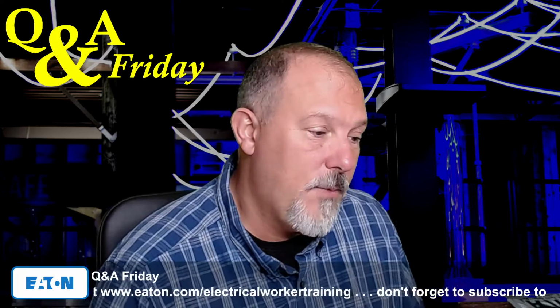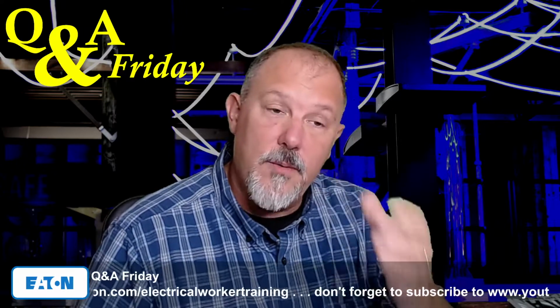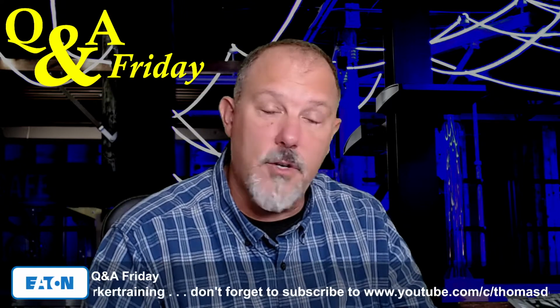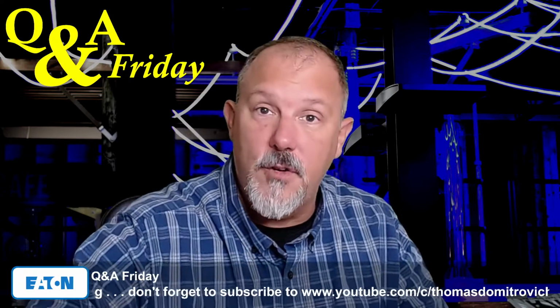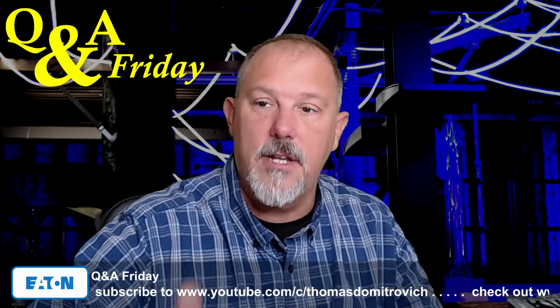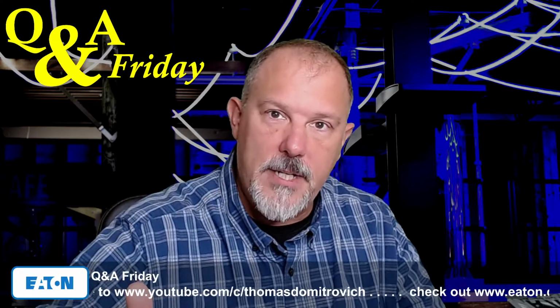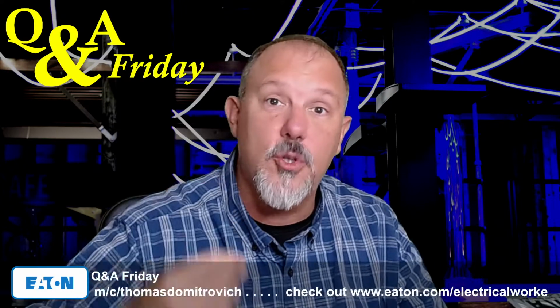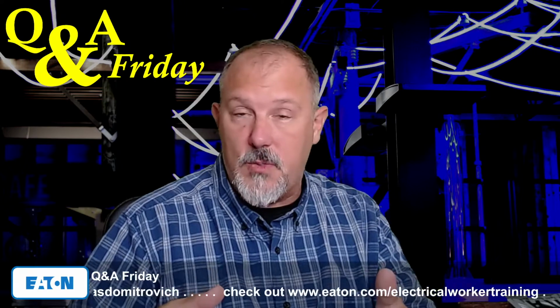But I was up in Michigan at NTI in Ann Arbor. We had some classes, and I was doing a technical. We were talking codes and practices. We were talking about overcurrent devices, the proper application, sizing of your overcurrent device, selecting the conductor, doing your ampacity calculations, picking your overcurrent protection. What is 80% versus 100%? Interrupting ratings, short circuit current ratings. What are the differences between those?